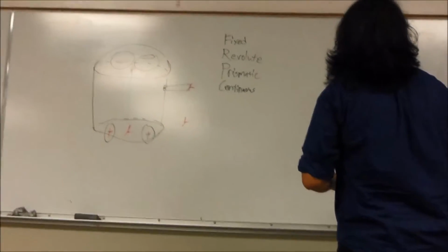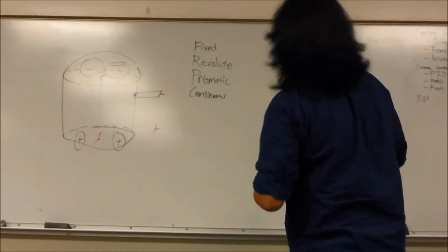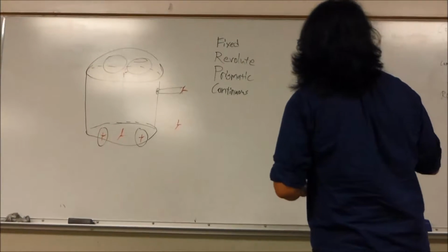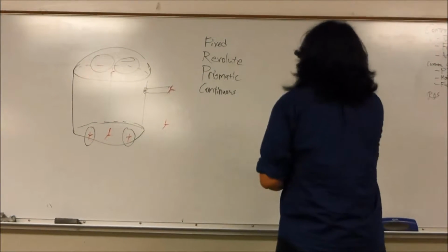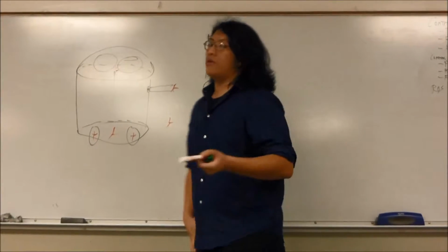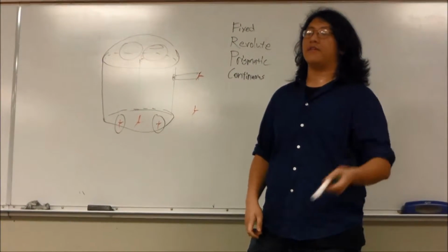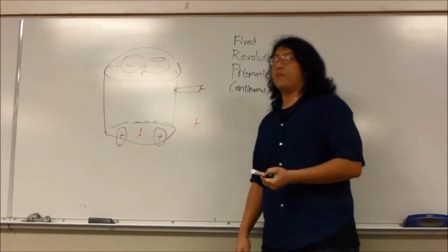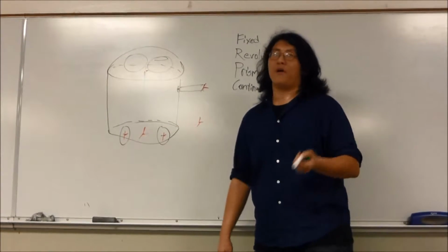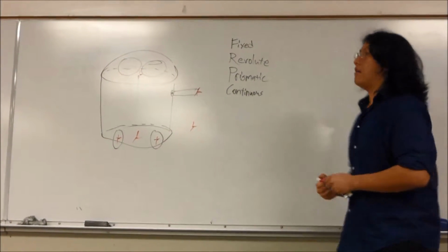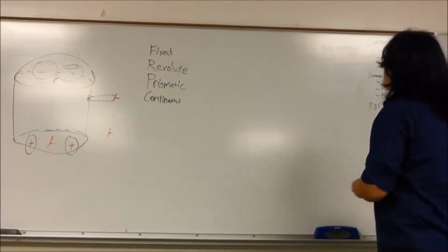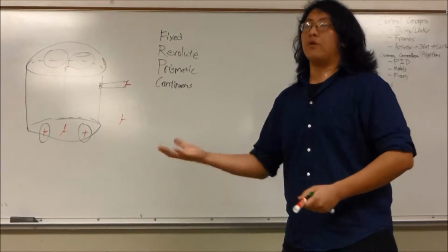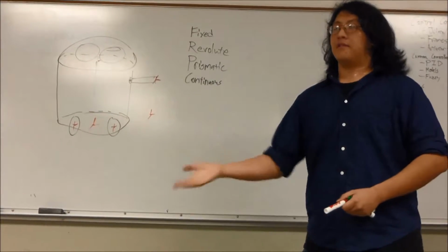Another thing that we commonly will have to talk about is different types of motion, what level that we're going to control things at. So when we deal with robotics in RAS, often we deal with things at actuator level, meaning I'm going to set my motor power up to 100%, 80%, something like that. This is what we will refer to as control in actuator space, where we don't know what motion it's actually going to cause. All we know is we're outputting power.